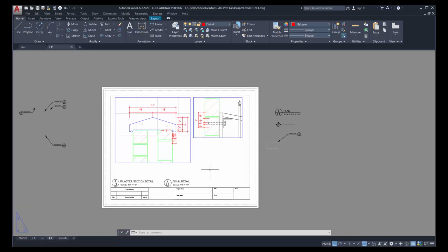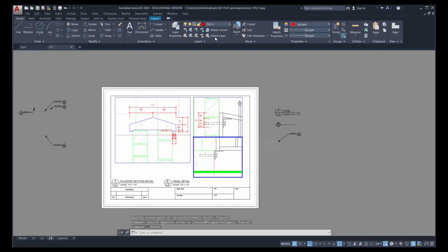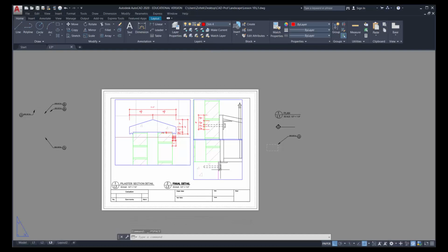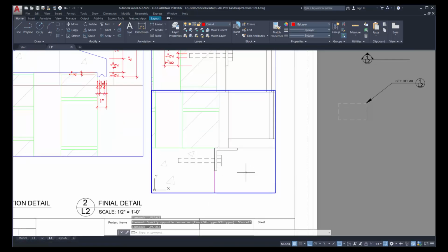This one's simple. I can copy the viewport straight down, just giving myself a little bit of room for the title reference. Now I'm going to slide that bolt up, double click outside, roll my wheel, zoom in on the page, double click inside. I could have copied those sets of dimensions. I will do my lower linear dimensions first. There's my 4-inch.